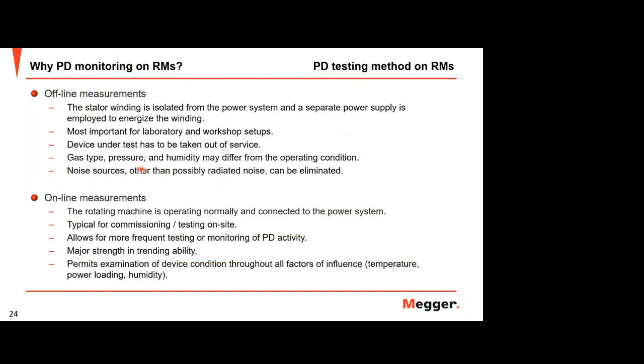Yeah, why PD monitoring? Because actually there are offline testing and online testing with some advantage and disadvantage, of course. So with the offline measurement, we refer to the standard IEC 60270, where the stator winding is isolated from the power system, and a separate power supply is employed to energize the winding.